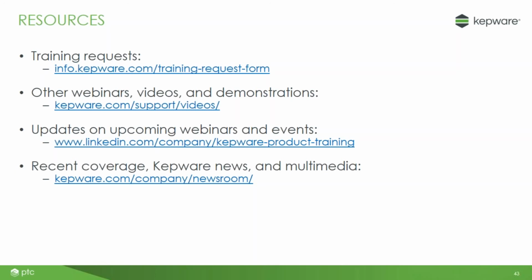It differs from OPC, different from REST, but similar type of functionality where you can browse through and see everything you have available on a remote instance of KEPServerEX, maybe out in the field if you're hosting a system on the cloud. That's really neat functionality, and it's facilitated through the use of a CSDK that we deploy on the Kepware side for that always-on connection.